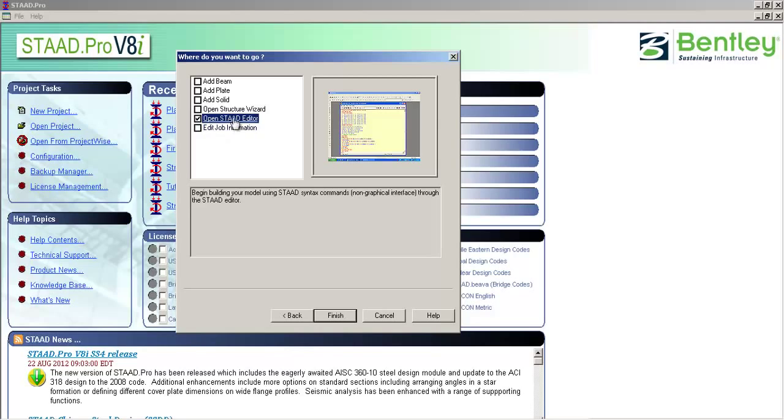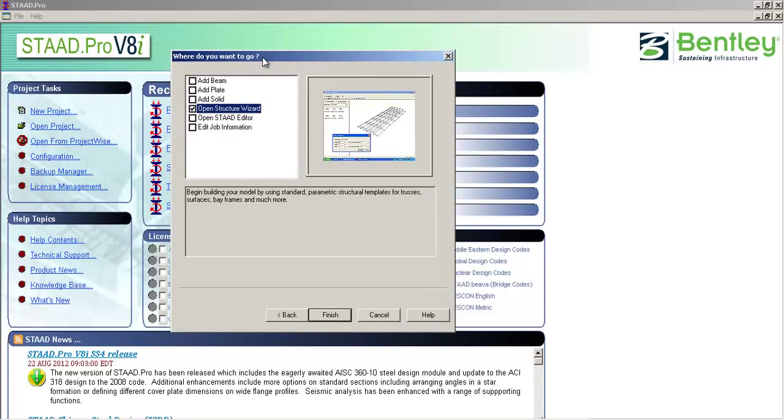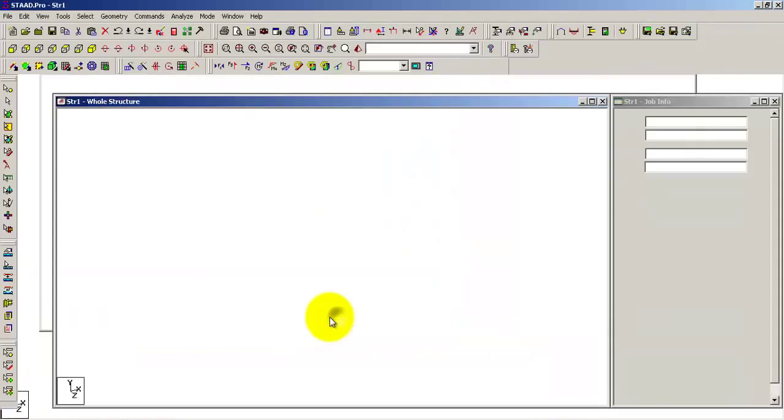You can see the picture in this. It helps in merging and importing the models given in this predefined models box inbuilt in the library. You can see the add beam options. We can add any structure which you have built in AutoCAD or any other irregular shapes. While in the structure wizard we have the software merge a predefined model. Here it is a stadium roof which the user is importing. So we would use the add beam option and click finish.